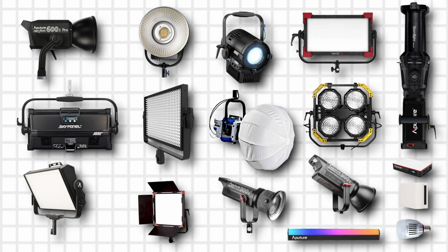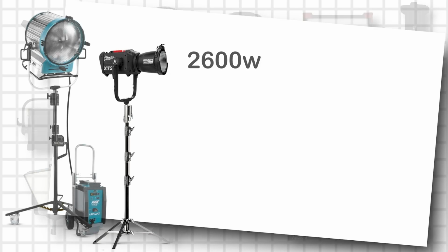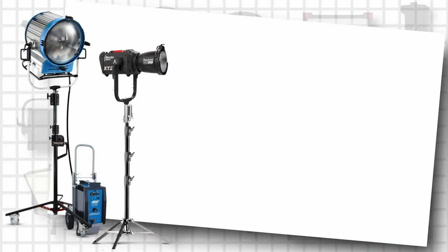This workshop will look at some of the incredible tools and advantages LEDs have. But first, let's look briefly at what they cannot currently do. This is a LED cob light, one of the strongest compact heads at the time I made this film. This is a 12K HMI Fresnel. As you can see, they are much larger, but they are also much brighter. Therefore, they have a much stronger and longer throw. Current LED production lights just cannot deliver the single point power of a tungsten or HMI.